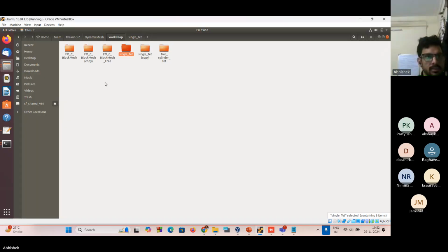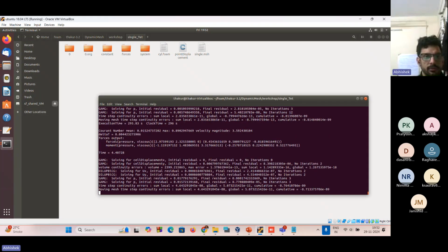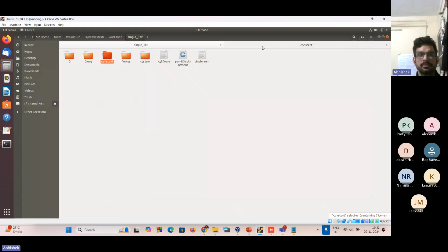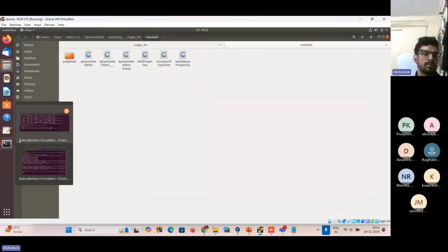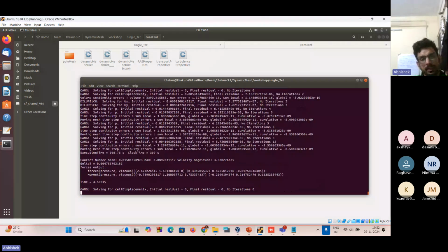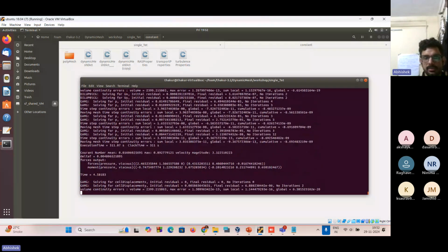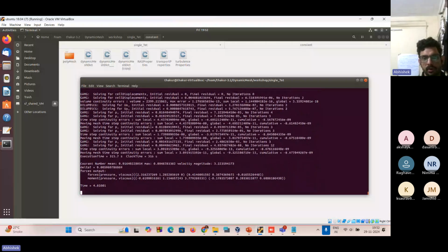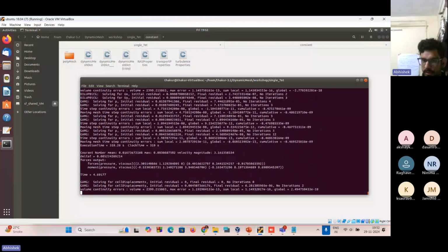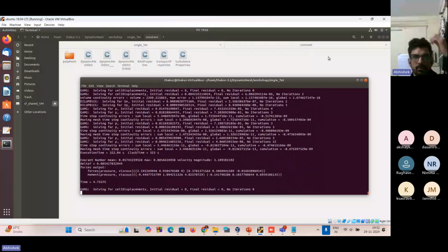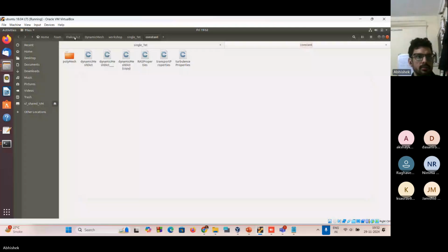All right. It is taking way too much time. So we'll move ahead. We'll see the result at last. The point of telling you this is that at some point, if we keep on increasing deformation, or if we have multiple cylinders like 4, 5, or a complex body, at some point mesh morphing will not work, and you will have to move to other topological changes like remeshing, mesh solvers, or others.